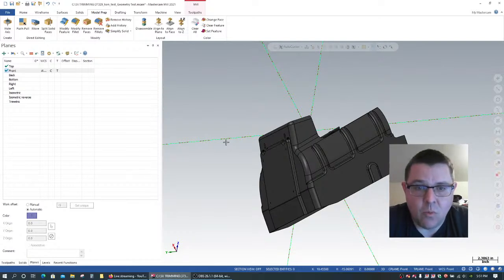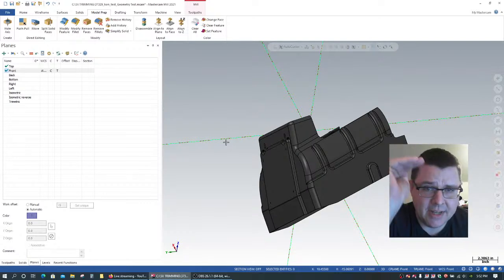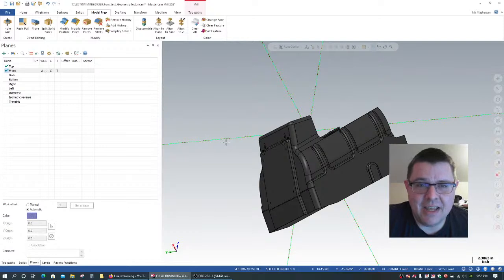Well, what is the waterline? The waterline is the place where the plane would basically float in the water, before it started leaking and water started rushing in. It's kind of the buoyancy point, what you could think of as the Z plane in the XYZ coordinate system. Everything that's at Z0 is at the water line in the plane. So in terms of doing aerospace parts, there can be some advantages to not moving the part.